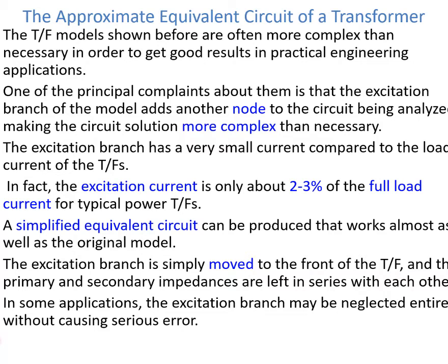Sometimes this transformer model becomes more complex because of the addition of another node, making the circuit solution more complex. But the good thing about this circuit is that the excitation current normally is about 2 to 3% of the full load current for typical power transformers.